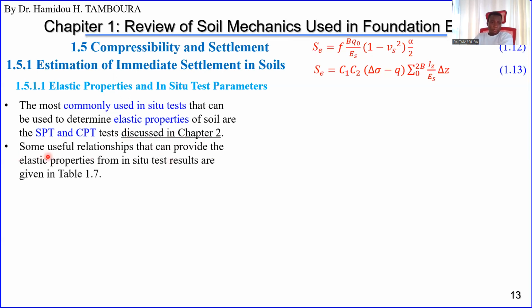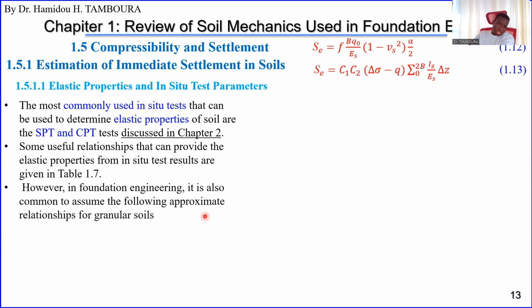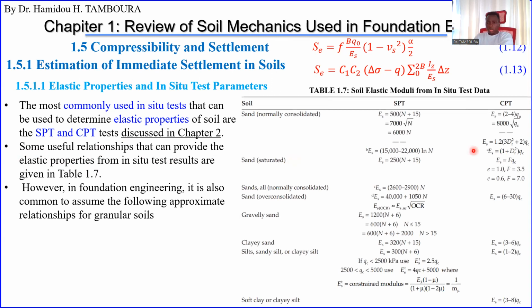There are some relationships in this table, for SPT and for CPT. For normally consolidated sand, you can use this formula if you have the SPT N value. If you don't know what the SPT N value is, the next chapter is mainly about field testing.